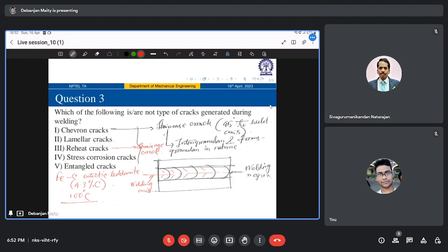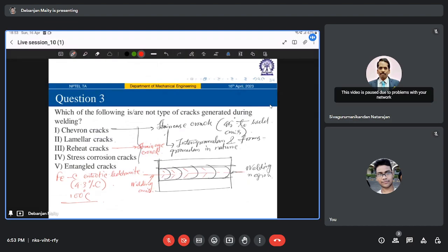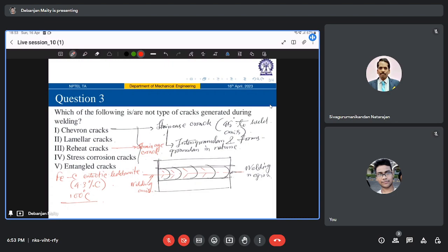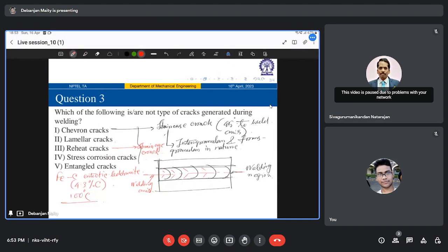So to age this weldment, you must first solutionize it and then quench it, and then you do the aging process. During solutionizing, the residual stress in the weldment is relieved, of course. However, it is quite possible for some aging to occur in regions of the heat affected zone that were solutionized by the heat of welding, since aging occurs at a lower temperature than stress relief, right? So cracking can occur as the alloy in this region age hardens, becoming stronger but less ductile, and is acted upon by stress to cause cracking. This phenomenon is called strain age cracking or simply reheat cracking.